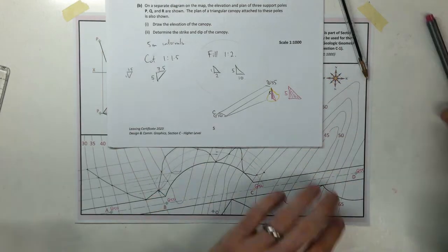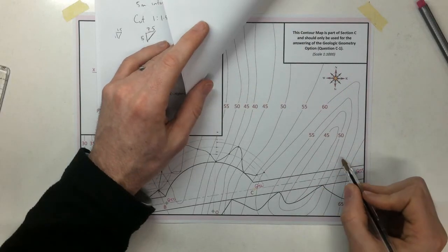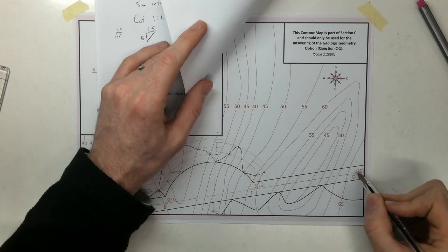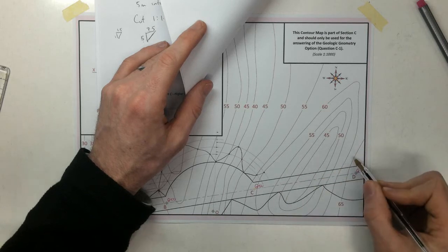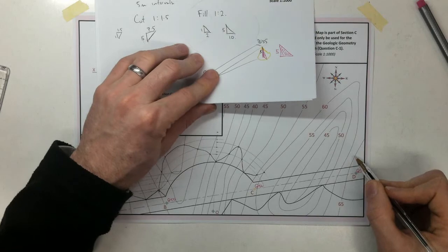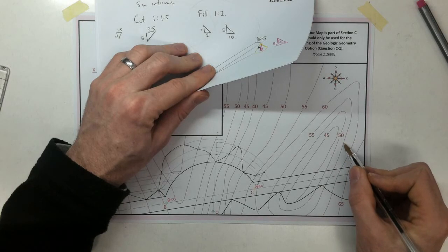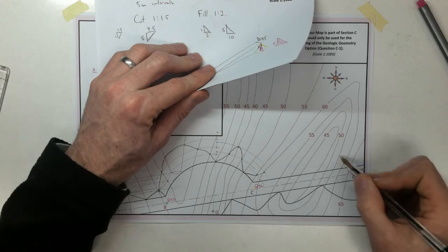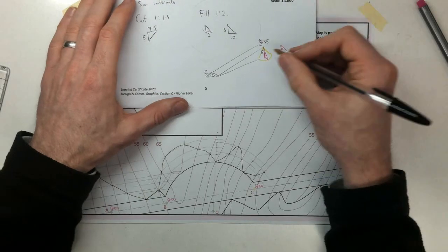We are looking at the heights here, all at heights of going from 50 to 45. So we're going to be doing a fill here, because all these heights, 50, 55, they're all underneath here. I'm probably going to have to find another cone for this side. So we'll deal with our fill cone here first of all.